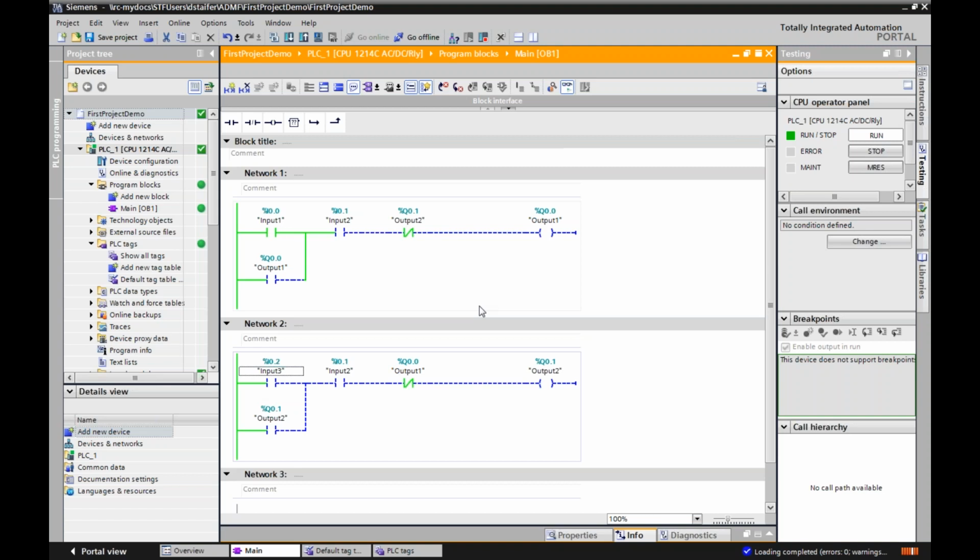Turn on a switch. Ta-da! That's running, and so keep that on. And if I try to turn on this other output, I can't. My other motor won't start. So now if I hit my stop button, it drops everything out. Now I can start my other.